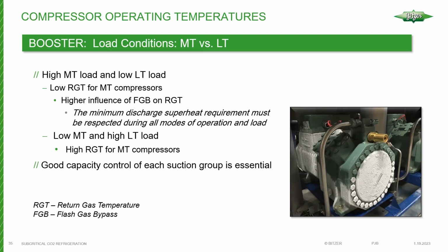but generally all these pipes are insulated in the CO2 system, of course, and with a high latent heat, and also the fact that it requires much more pressure drop compared to HFC refrigerants to boil off that droplet of refrigerant, it's safe to say that that refrigerant is going to end up at the medium temp suction. So there needs to be a good source of heat to offset that. So that's where it can be a little more challenging.